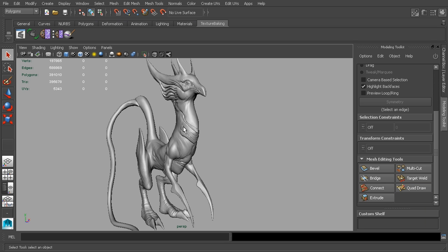But first, we have to tell Maya that we want this to be the object that all of our geometry is going to snap to. Now, in the past, we've done that by choosing a transform constraint and putting the object in there. But in this version going forward, we're going to actually make this live. So if you've used Maya before, you're familiar with Make Live probably. It's taking an object and making it so you can do other things that are constrained to that object. And so that's sort of been consolidated.